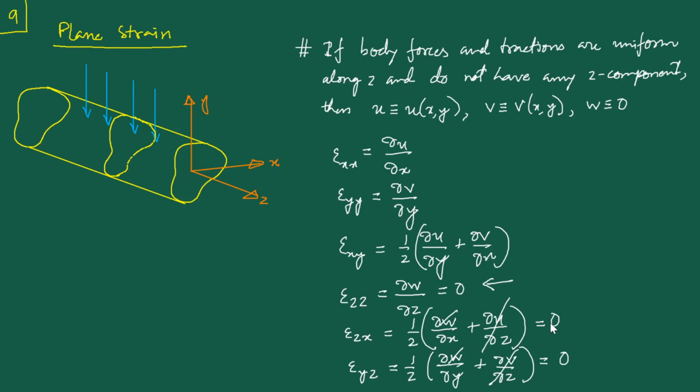All right. Now, what we want to do is proceed in a similar fashion to the plane stress case. First of all, what we note is what simplifications the fact that epsilon zz is zero, among other relations, affords when we talk about the constitutive law, basically the generalized Hooke's law? So let's consider that in the next page.